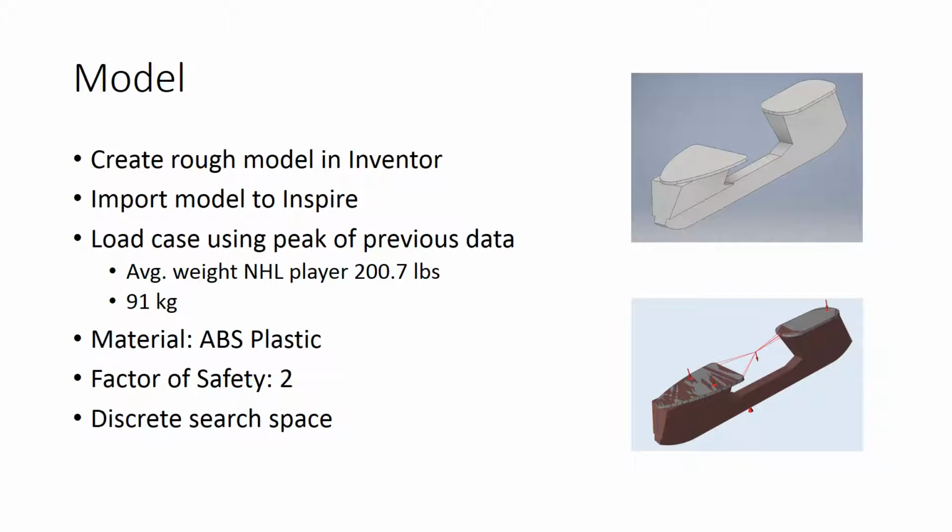To develop a model, I created a rough model in Autodesk Inventor. Accuracy to a current product was not necessary, as most of the material would be removed during the optimization. This model was imported into Altair's Inspire, and a design space was created.